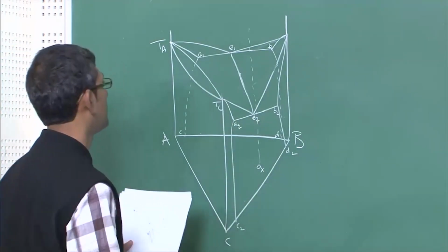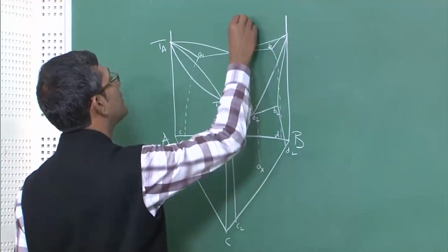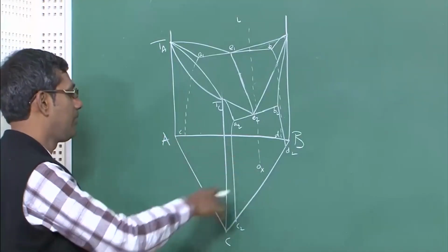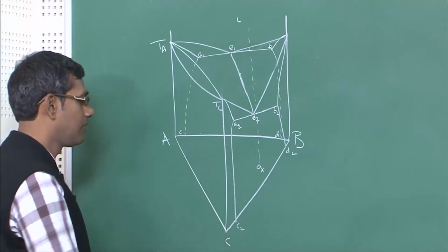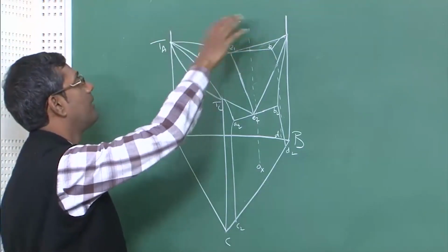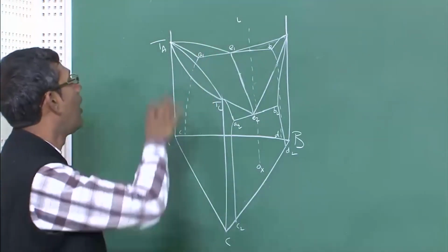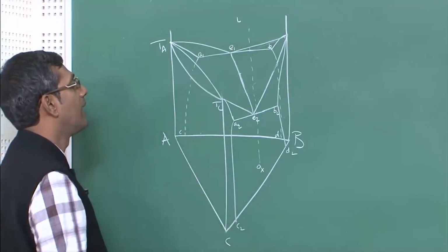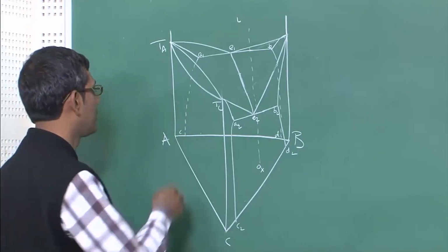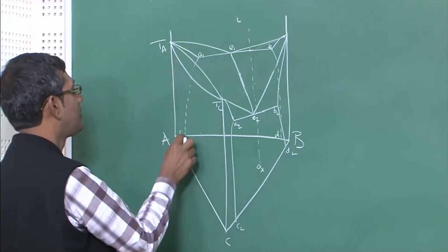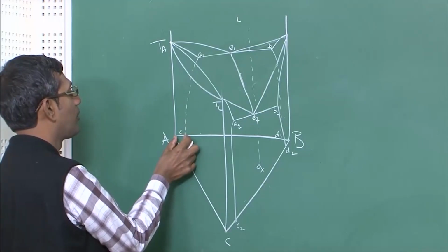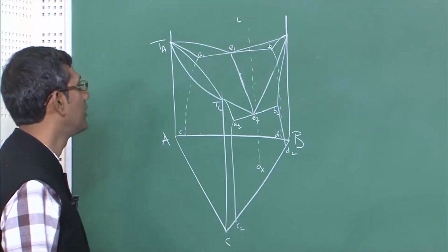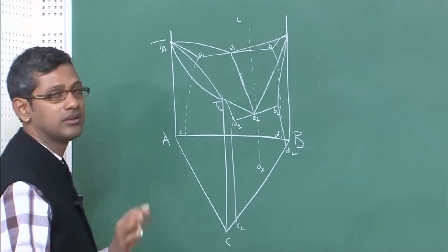Now, what is going to happen? First, this is a liquid, as you have seen that this forms a complete, miscible liquid at higher temperature, and at lower temperature this forms solids of different compositions. You can see here, the A-rich alpha phase will have this much solute concentration, B-rich will have this much, C-rich will have this much concentration. But in the liquid it is all miscible together.